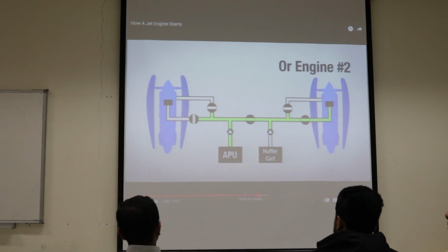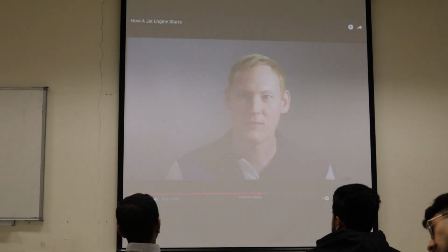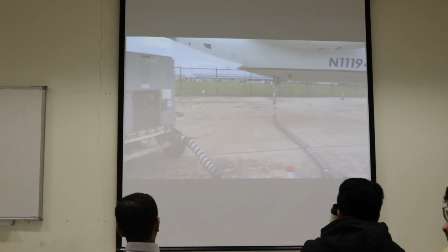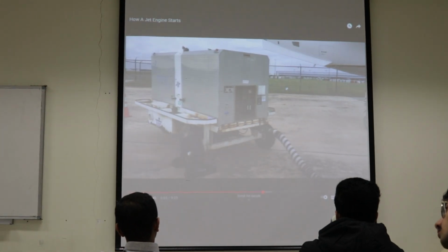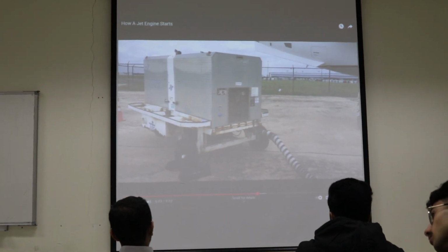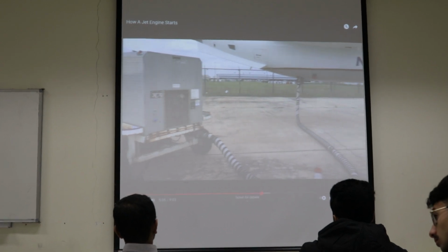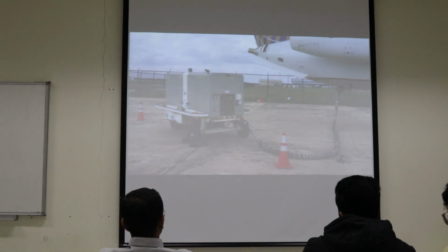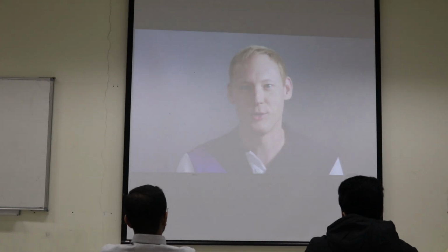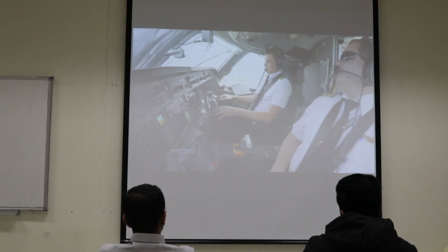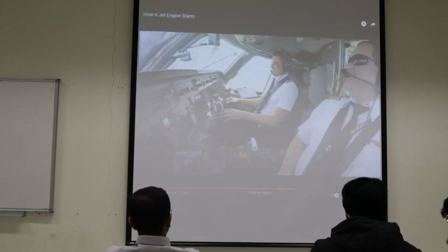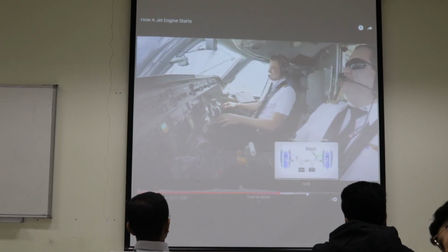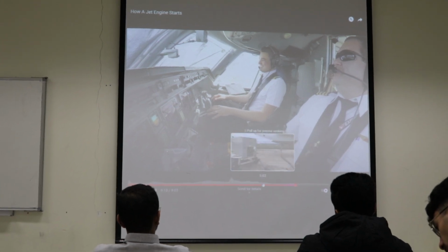You can see it here, Shabab. We have a compressor that can supply compressed air to the air turbine, and then the air turbine can drive to start the engine. Once we start one engine, we can take compressed air from any bleed air, we call it bleeding air, from any stage of the compressor, and then we can move the compressed air to drive the air turbine to drive the other engine. Because usually we have two engines, in most of the cases.